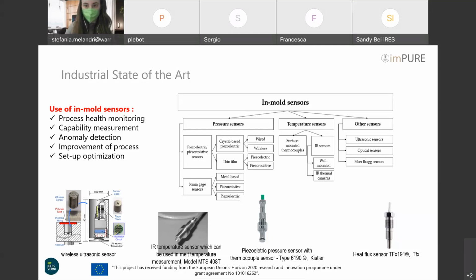When the cavity is filled, the hydraulic pressure required increases very quickly. To avoid an involuntary opening of the mold, the control mold switches to a forced hydraulic pressure. This is the packing phase. The point of transition between the filling and the packing is called the switchover point. It's quite an important point for setup for operators. At the end, the cooling phase, without any pressure applied, takes place before the mold is opened and the part ejected.